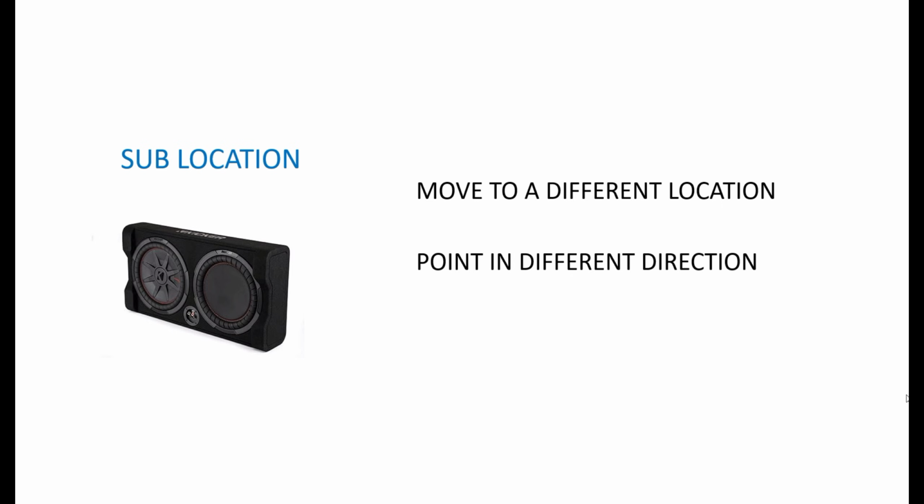So it doesn't always mean, in a sedan for example, maybe firing them up or towards a seat opening or something might work better. And it also depends on what type of box you have your subs in. Ported boxes are more sensitive to direction than sealed boxes. Okay, but yeah, in the main, the best way to aim your subs is towards the rear of the vehicle, as opposed to firing them towards the front, just because of boundary loading. Okay, so moving on.